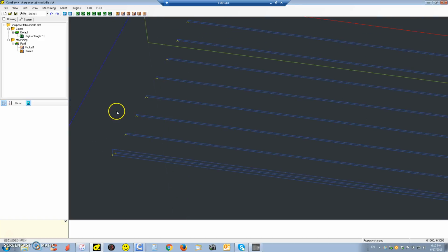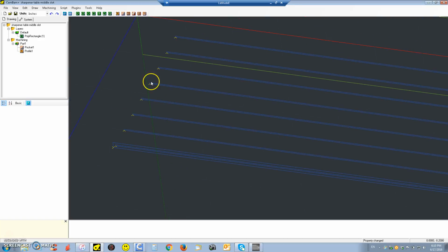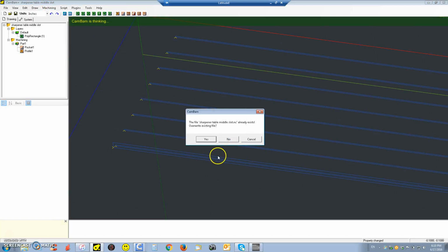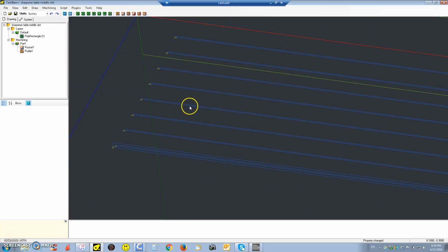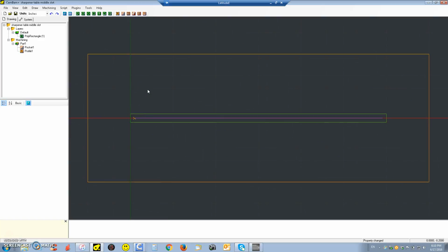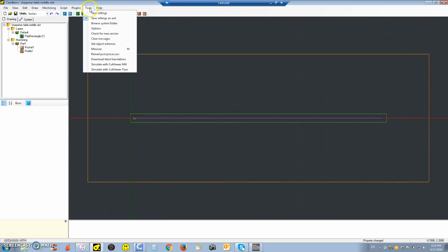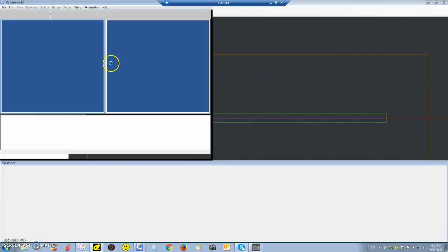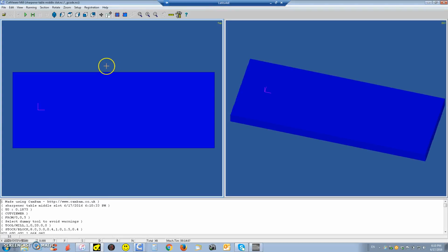All right. So obviously what you do is you generate the G code when you're done. You say generate, produce a G code, and that's what Mach3 reads, this G code. And so I just did that. And what's interesting is instead of trying this on the mill directly, I could try it on a virtual mill. All right, so I'm going to do this, and here's the virtual mill. It loaded the G code that I generated down there.